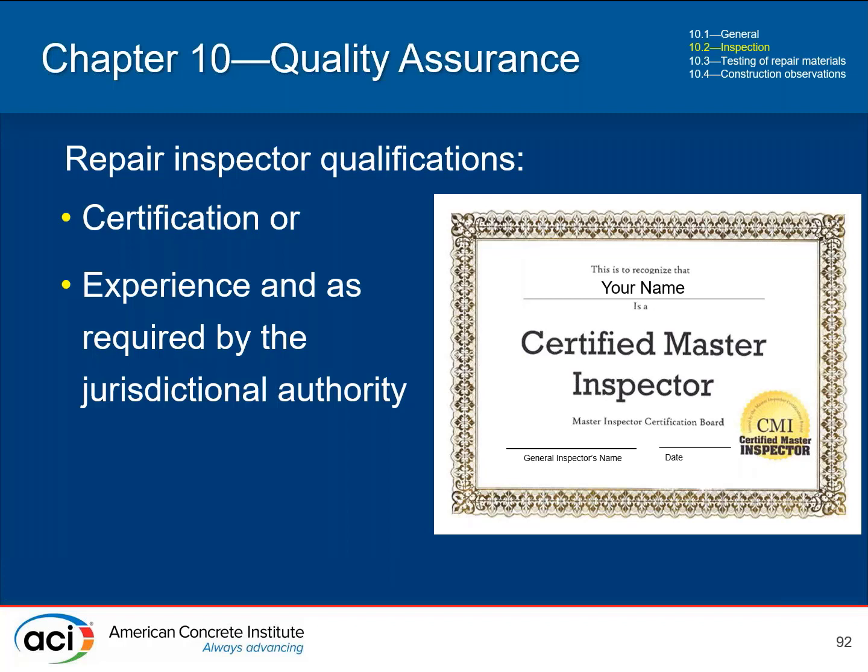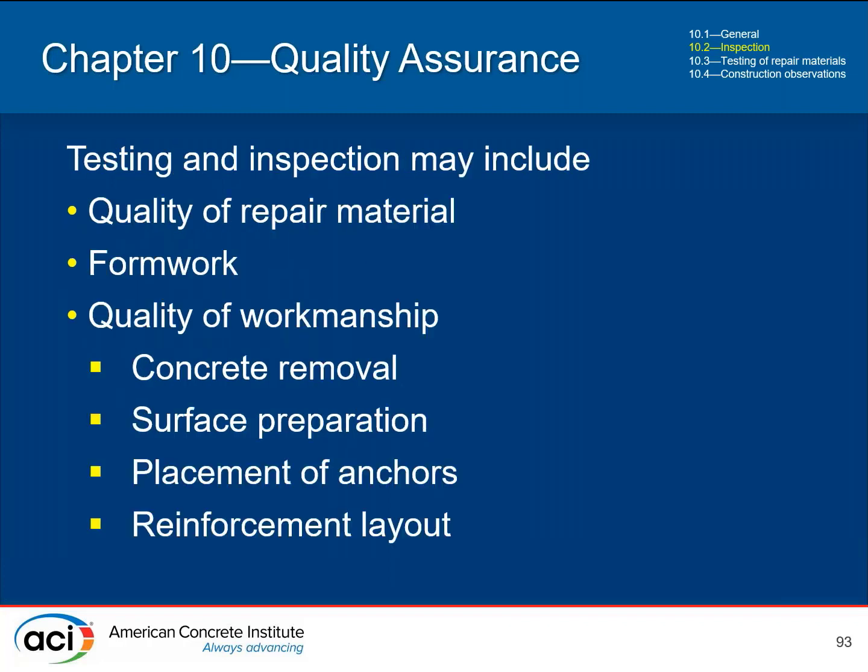And some of this is outlined; the jurisdictional authority may have an opinion on what's an appropriate repair inspector, but there are certification programs. I know ICRI does have an extensive program that qualifies someone to be a repair inspector. And that should be implemented, made very clear as part of the project, either in the construction documents or the discussions with the owner, that this needs to be done, and it needs to be the right person. It's not just your maintenance guy going out and having a look at it.